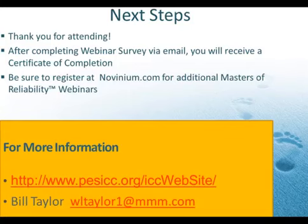It came from Ted, who wanted to know, will partial discharge testing pick up potentially bad splices and terminations? Yes, if done correctly, field partial discharge testing can pick up and detect issues with joints and terminations, and potentially tell you that you can have issues with them.